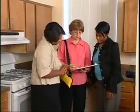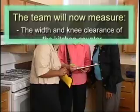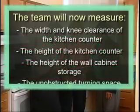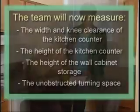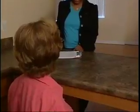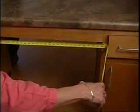The survey team is now ready to survey the kitchen. They will measure the width and knee clearance of the kitchen counter, the height of the kitchen counter, the height of the wall cabinet storage, and the unobstructed turning space. Is there at least one 30-inch wide section of the counter with knee clearance? All right, let me check that for you. I've got 36 inches wide.